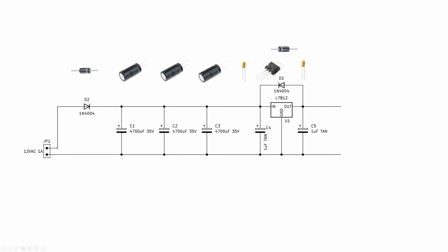Finally, to visualize that we do have voltage on our output, I added an LED. A resistor, to limit the current through the LED, is added in series. And that was it for the positive part.